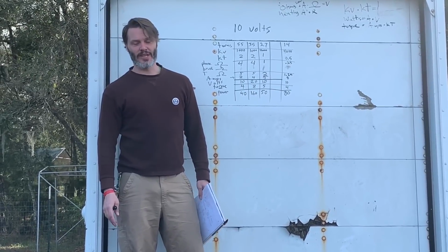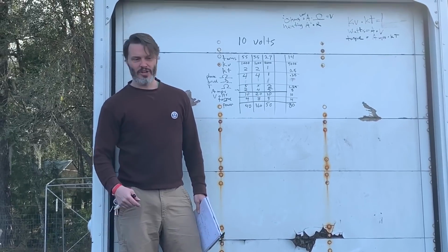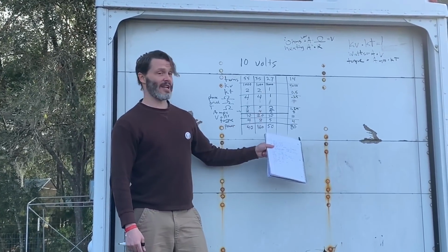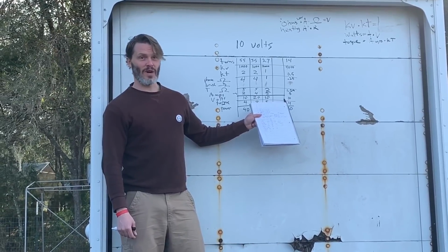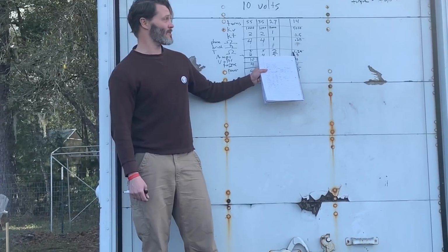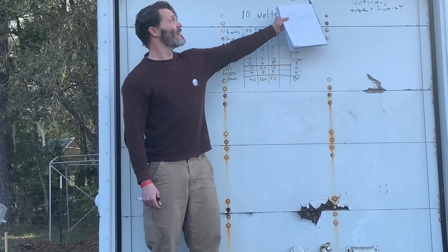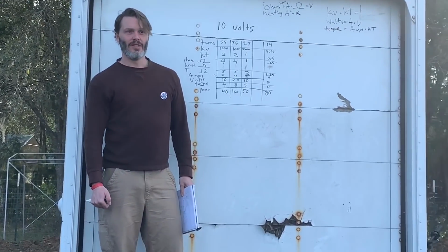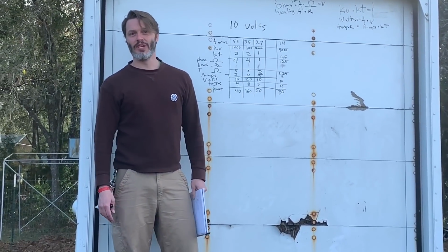And so what ends up happening when you're on the trail, well, you're only giving it a little bit of throttle, but that really fast, high kV motor still asks for a lot of amps. It asks for twice the amps. Let's say we go from 2,000 to 4,000 kV, it's asking for twice the amps. If we go up here to our heating, it's 4 times the heat in your ESC because it's a squared factor. And that beats on ESCs really, really fast.